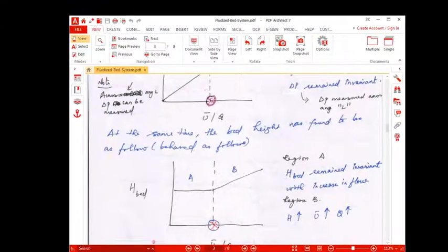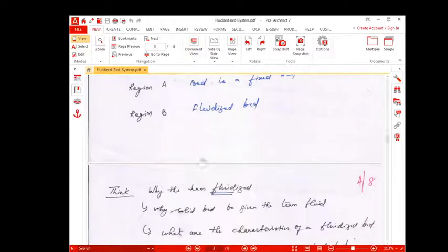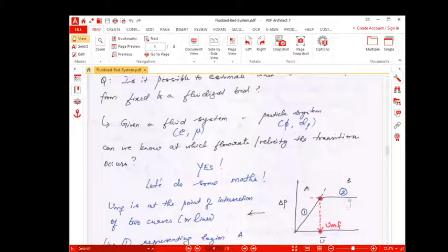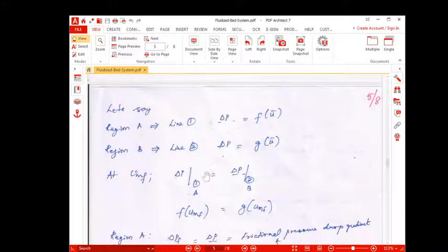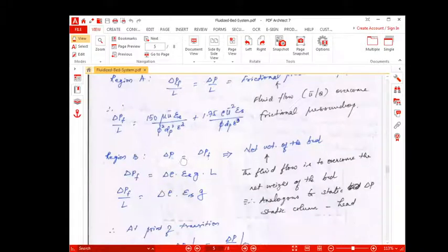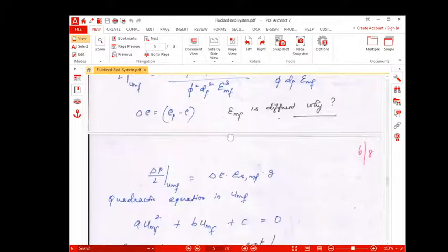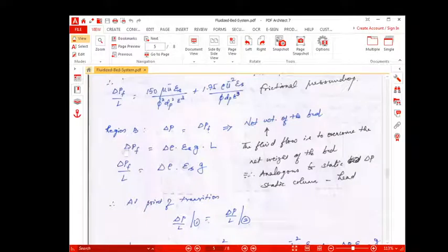Yeah. So in the second part, the equation for the second part, all the fluid that's flowing through supports the net weight of the bed. So the drag force per unit area, which is eventually the pressure, of this static bed that is supported by this upflowing fluid, is just equal to the net weight of the bed. And that's given by this expression.